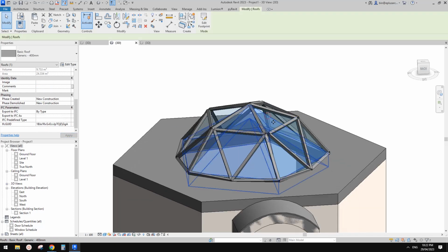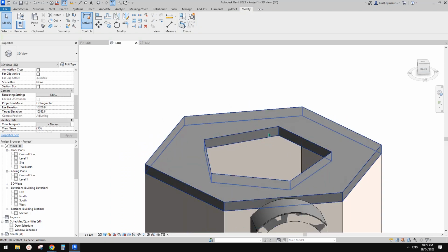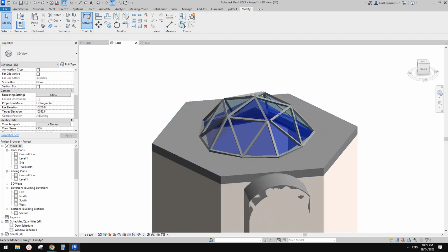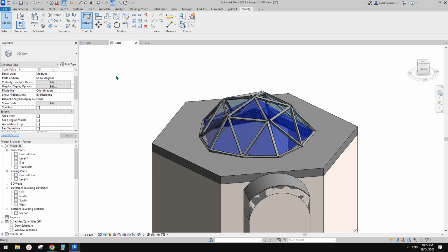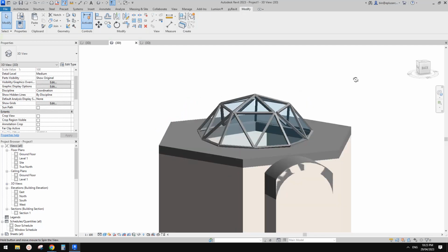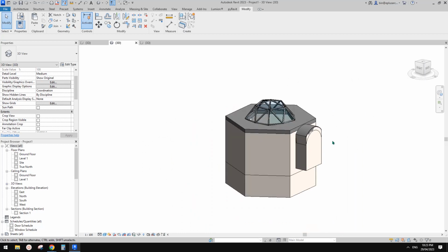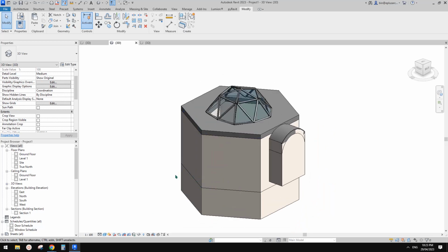So sometimes you probably don't want to have this roof, so you delete it, and you also delete all these adaptive families. So how can we resolve this issue? It's very simple. Just select all these, Control X, and paste in the same place. Now all these families are just floating in the air, not placed on anything. So you can delete the roof. Okay, and that's it. Yeah, it's quite ugly, but just some ideas.